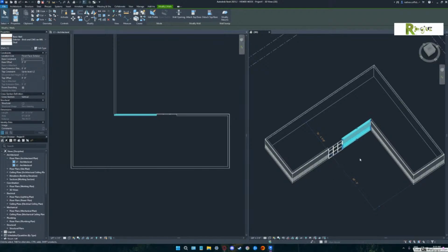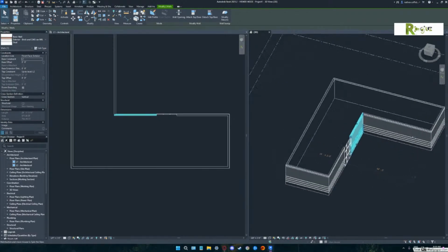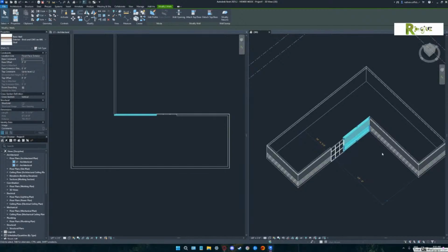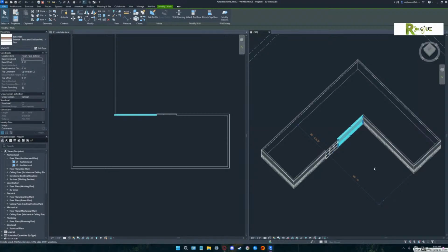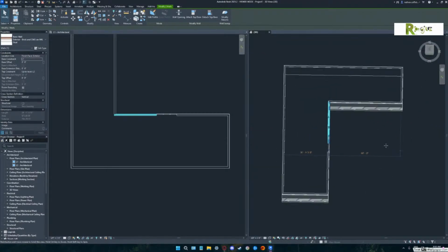And you see how it pulled that whole wall forward? Now the one that takes a little bit of getting used to is, in order for it to make that 60 feet, it takes the wall you selected as the one that you moved. So maybe you actually wanted your building to get longer. So you would pick that other little end wall, the top one. The 60 feet should show up again. But now when you turn it to 70 or 50, it's going to move the wall that you had highlighted. See that?